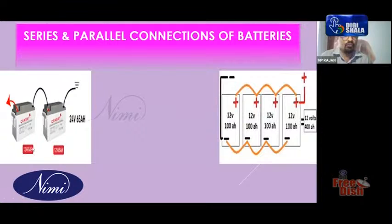But this is a 12 volt 65 Ah battery. This is also the same. Your ampere hour capacity is the same, 65. That means ampere hour capacity will remain the same. Whereas suppose you want 12 volt only, but you want more current to be drawn from the battery. In that case you can connect the batteries in parallel. So 4 batteries of 100 Ah connected in parallel, 4 into 100, gives 400 Ah capacity and the voltage remains the same. This is exactly the same as the solar power system.